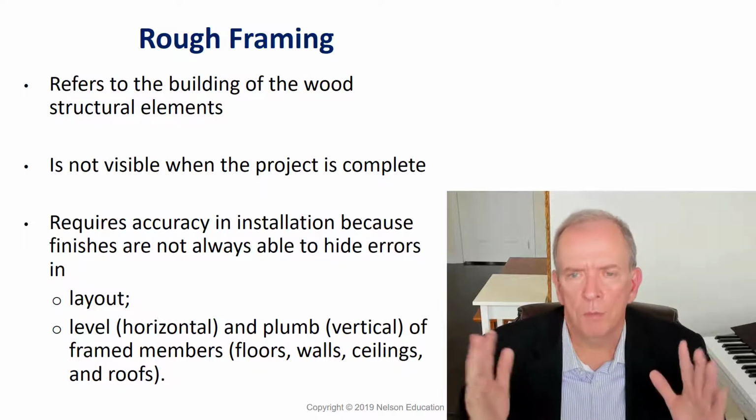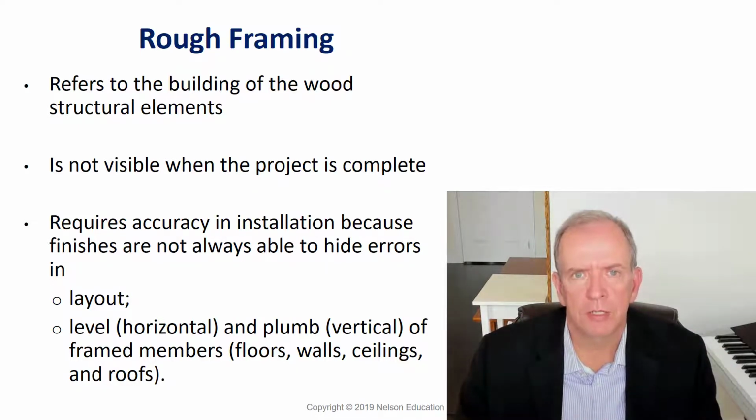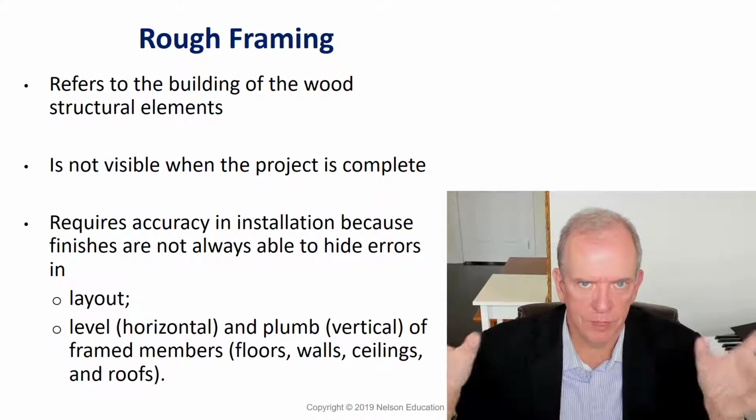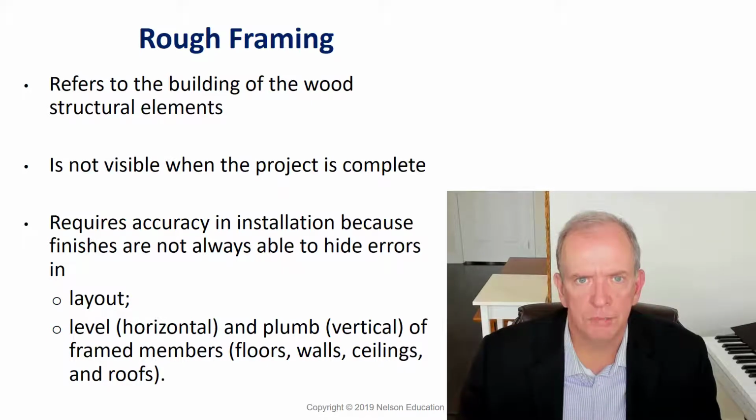And they were much more resistant to racking, the way that the construction process was done, whereas post and beam is not so resistant. Because you've just got posts, it tends to collapse much more easily, depending on how the post connections and beam connections were done.